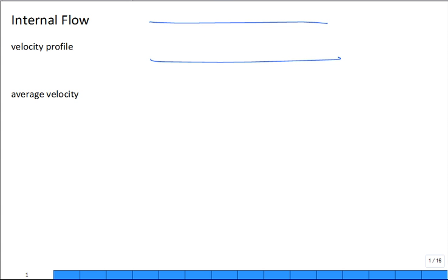You think about the center line of the pipe. That's a bad looking center line, isn't it? You characterize the radius r going from the center out to capital R, the inner radius of the pipe. And we're interested in predicting the fluid velocity profile. Where will it be maximum? In the center line, right?